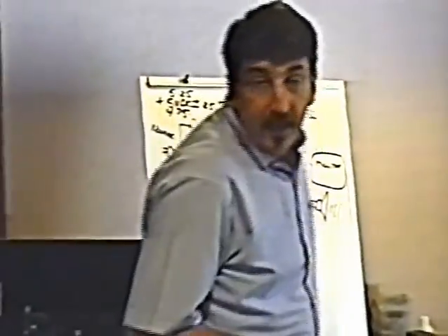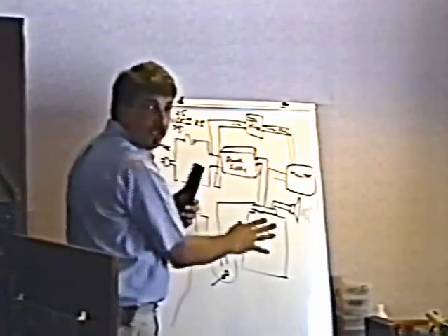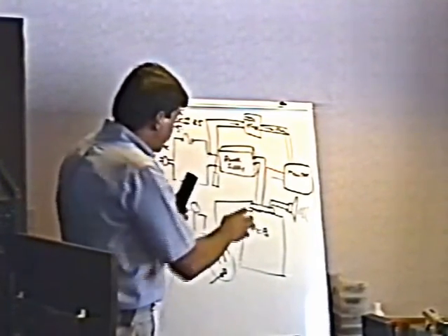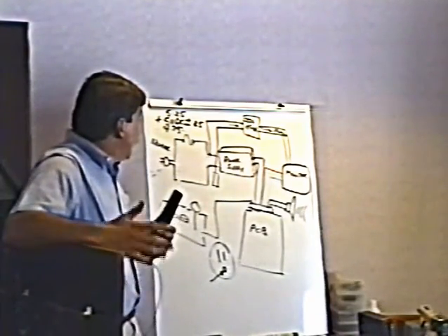I put the red meter lead there. I put the black meter lead up here on this one. And with my meter set there, and the power turned on and everything, I adjust the 5-volt power supply like that. So that's a good place to check the 5-volt power supply, because that way we're checking it on the board. And I adjust it so that it's exactly 5.1 volts on the board, and then I know that I've got my proper voltage.